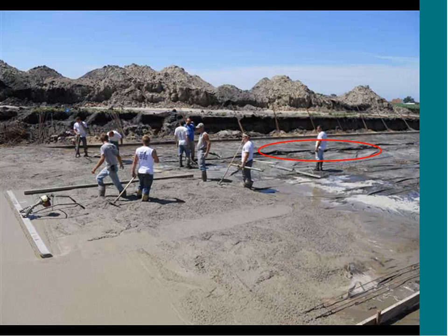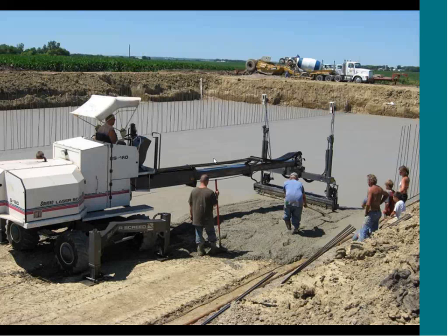And this is a good photo to look at when they have a synthetic liner or a poly liner going in. You can see where the circle is. It might be kind of hard to see, but there's a very large fold in the plastic. That is not going to give you a continuous thickness on the floor. Something that needs to be mentioned and talked about before they get any further with that concrete.